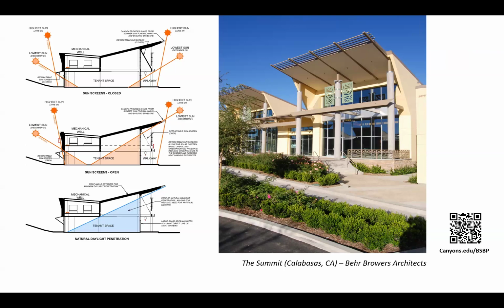No, we've seen that with some projects in the Midwest that used building integrated photovoltaics, where the solar panels are forming part of the facade or part of the roof, which is great when it's brand new. But then if the panel fails 10, 15 years later, trying to find a replacement for them is really hard. So you end up with an array that kind of half produces electricity and hopefully isn't leaking too much airflow if it's part of your building envelope.